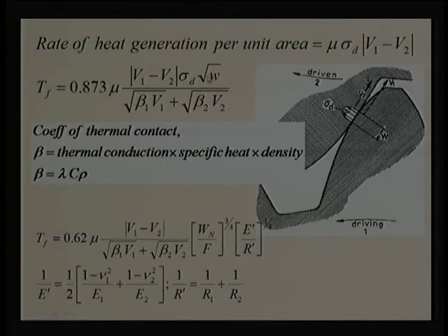And this small w is the patch contact length, which in our earlier lectures we represented as b or 2b, 2 into b. This was the contact patch length. If you refer to an earlier lecture, you will get a similar expression to what we are doing here. That is the elastic effective radius of curvature and effective Young's modulus. When you substitute, we are going to get the same relation.